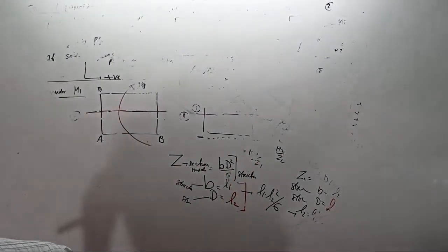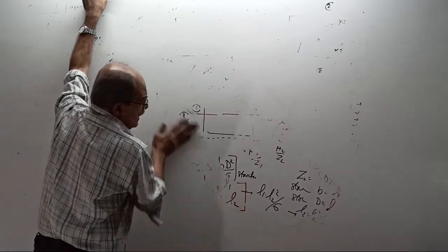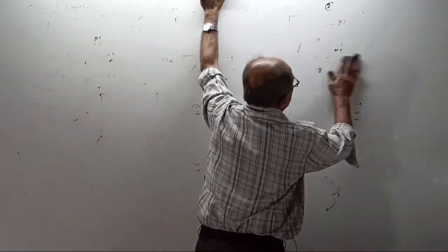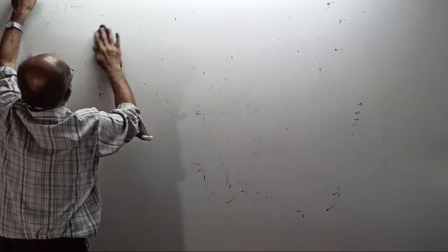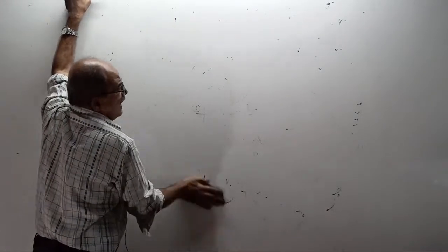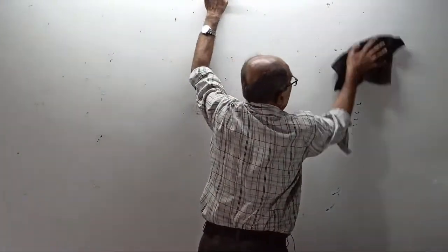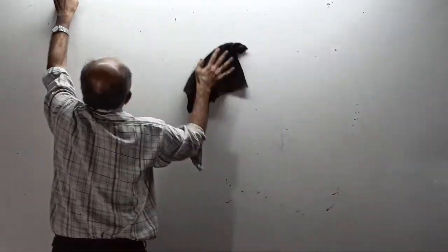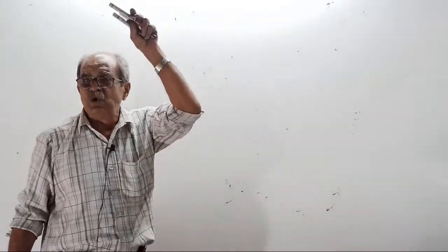Okay. I will start. When you design the footing slab, when from the column you get P, M1 and M2, how it comes we will see in the software class later. Then there are two pressures you have to consider. One of them is gross pressure, other is net pressure. When you want to check the safety of the soil, or when you want to check the stability, or when you want to ensure that pressure on soil does not exceed SBC of soil, then you have to consider gross pressure, where weight of footing also is considered.